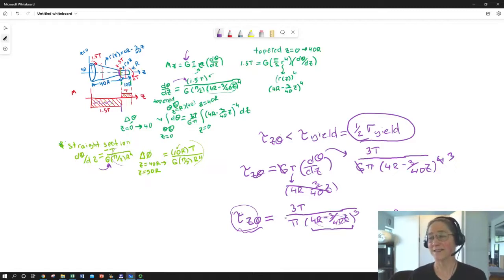So that's an example of how you can apply our torsional elasticity to a different profile shaft. And again, any function of your shaft profile could be accommodated. Any continuous function that you can integrate, take the derivative of, manipulate is fine. Finite element would allow you to literally do anything. Anytime you have a discontinuity, of course, like you do with any other mathematical discontinuity, stop, do a piecewise integral